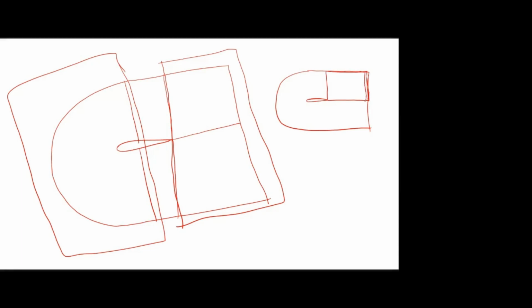Instead of coinciding, if you draw the profile like this, then this portion will be created as a separate one. Similarly, if you are drawing another profile here and doing the splitting, these two lines also should coincide properly. If you don't coincide, there may be a small gap, and this will create a separate phase. Like that, this issue will come.